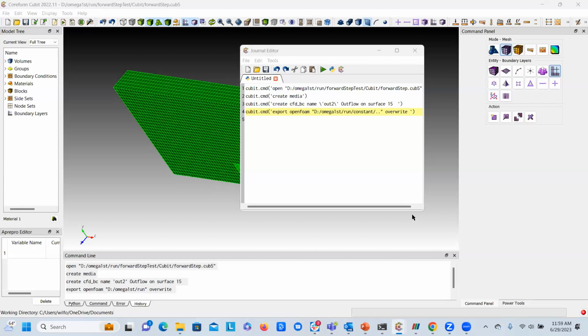Yeah, and in fact, there are other grid generators that you can use for OpenFoam. Gmsh is one. Gmsh, again, it's fairly simple. It doesn't give you the flexibility that Cubit does, especially on cleaning up your geometry. If you're getting something back from, for example, SolidWorks, and you convert that to a STEP file or a SAT file, you're going to always run into small problems, either small slivers, things that aren't just quite right that you have to fix. And Cubit gives you that opportunity to fix those problems and generate the mesh once you've got them fixed.